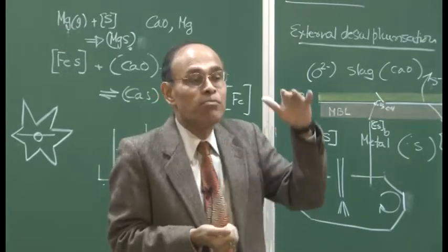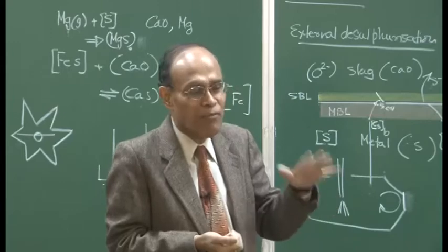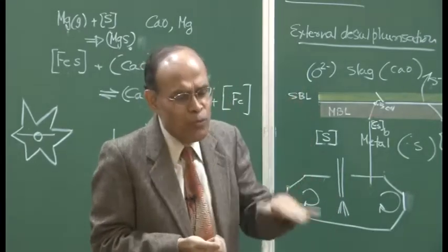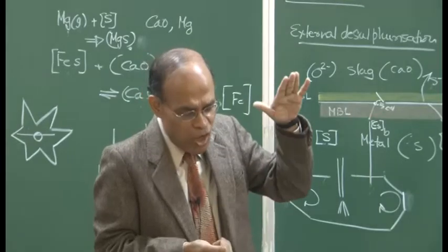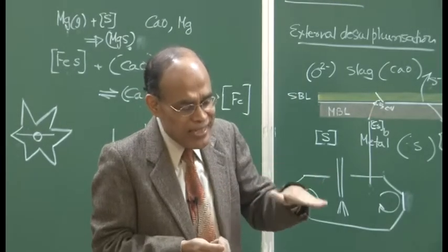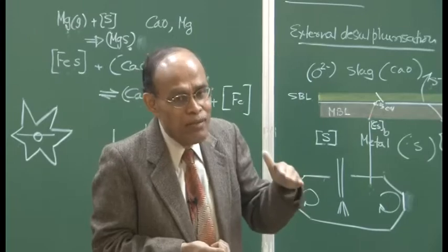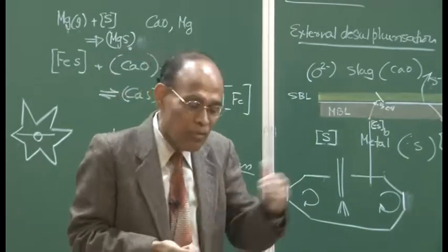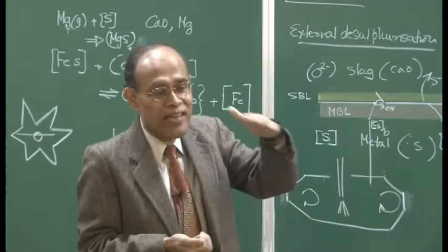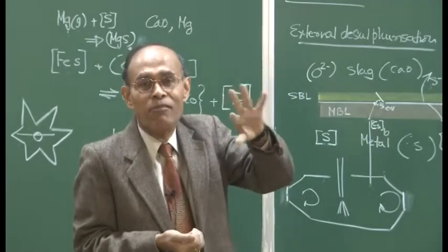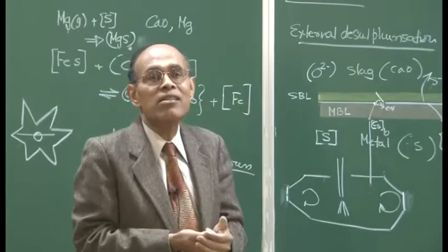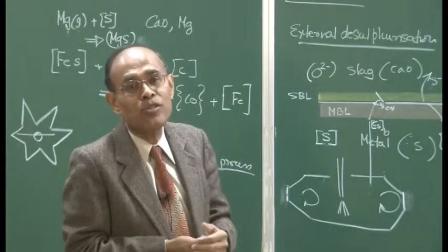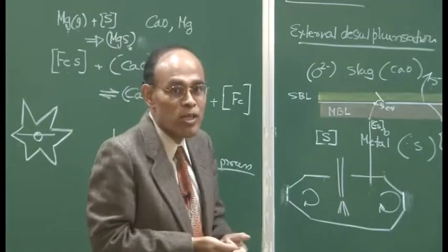Since the blast furnace raceway temperature etc. fluctuates, raw material fluctuates, and if the blast furnace is not able to produce, the engineering is not so good, and it is not able to guarantee a fixed silicon on a daily basis, pretreatment will give us an option to remove silicon and thereby result in a hot metal which will have more or less a similar dissolved silicon, just enough to supplement the heat requirement of the steel making process.